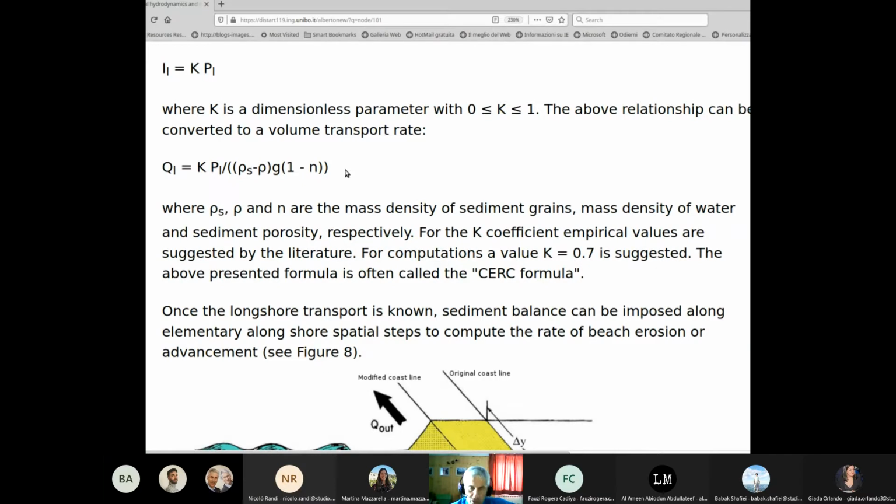You refer to a wave height, a sea bottom depth, some porosity and mass density of the sediments. These change if you move along the beach. Think, for instance, about the angle alpha b, which is the angle between the wave direction and the coastline. This angle continuously changes, which means that you have to change the value in the formula that you see on the screen. Even if you move like 10 meters, the angle may change.